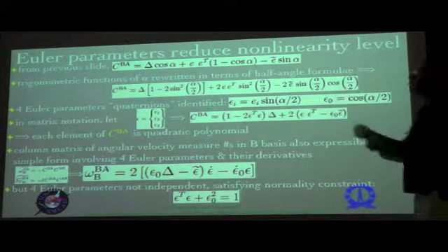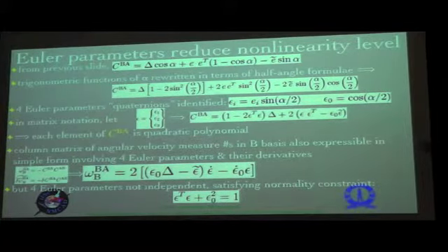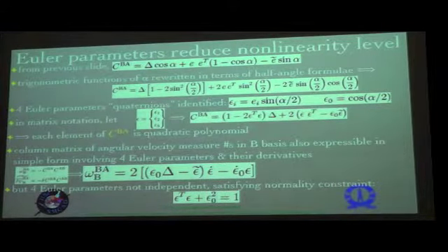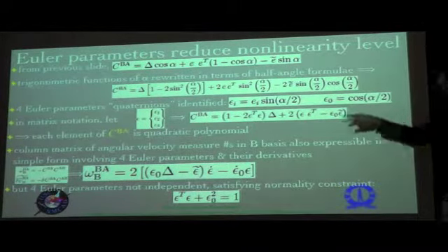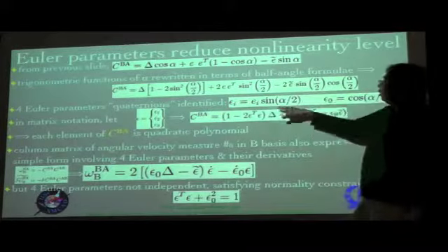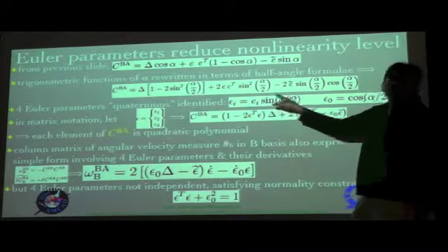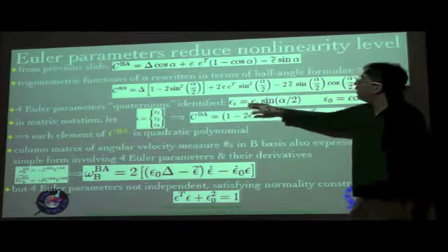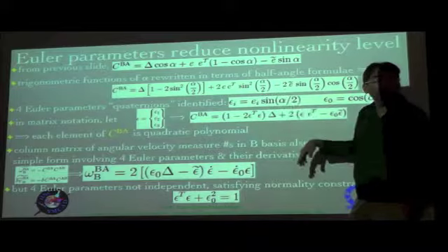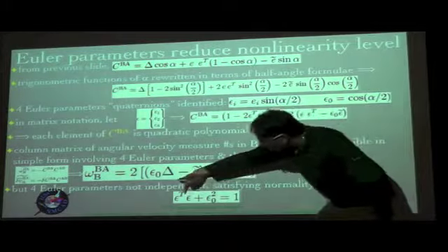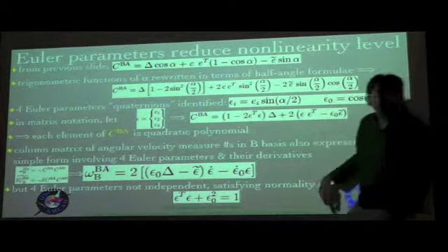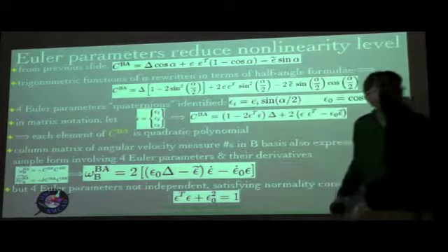Similarly, once we have replaced the E's and alpha in terms of the epsilon, we now have 4 Euler parameters, which are epsilon naught, epsilon 1, 2 and 3, and they are related to each other and satisfy this condition. It's quite easy to see because epsilon naught squared will involve a cos squared alpha by 2, whereas epsilon transpose epsilon will involve E1 squared plus E2 squared plus E3 squared times sine squared alpha by 2. Already we know that the sum of the Ei squared is equal to 1 because it's a unit vector, so that's its magnitude. And then you have a sine squared alpha by 2 plus a cos squared alpha by 2, so that basically means it is equal to 1.